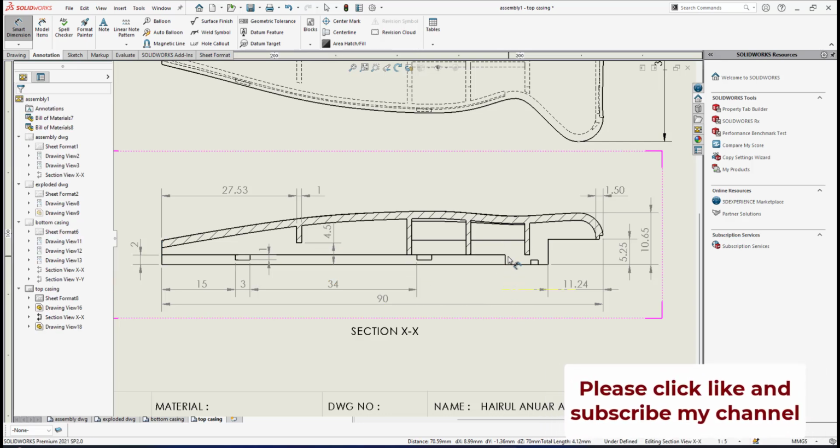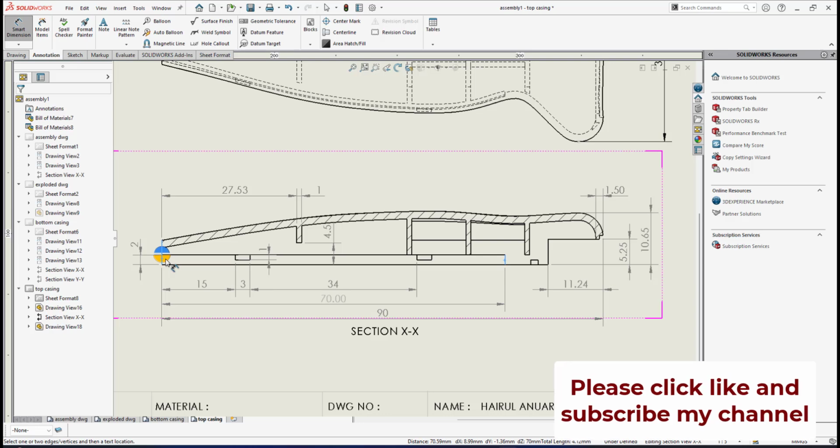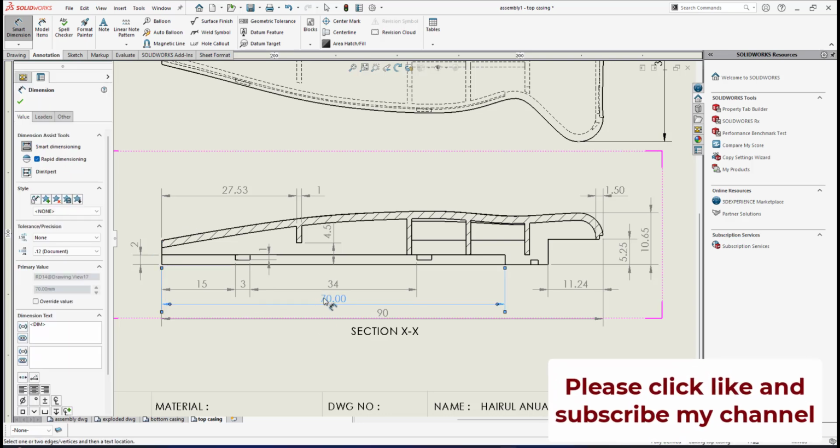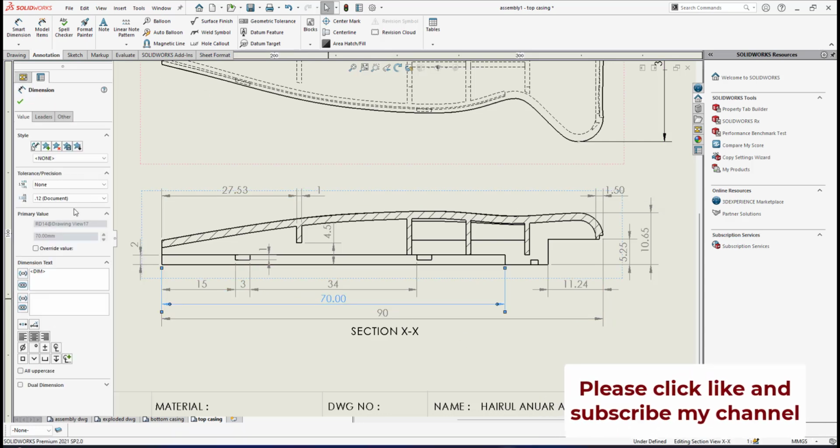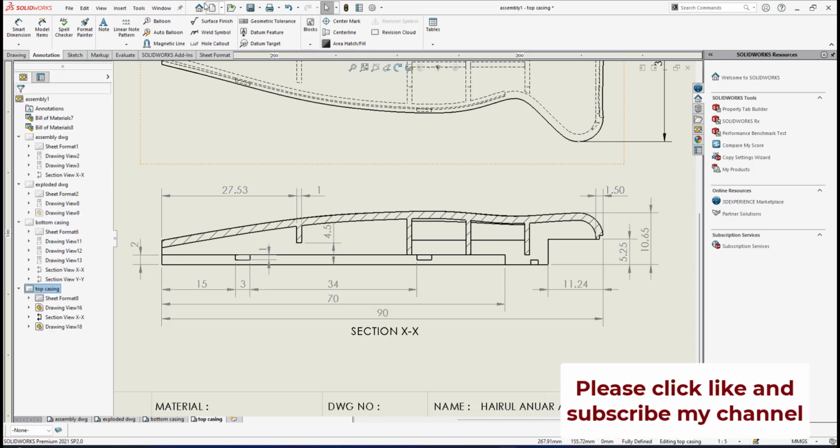If I put the dimension from this to this edge, I have this icon. If I click to the bottom, SolidWorks automatically tries to fit the dimension 70 into the right position. So everything is shifted to the right position, right? So about the 70 here, I can go no decimal point. It's already there. Then let me save my file again.